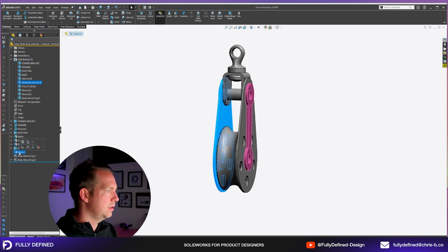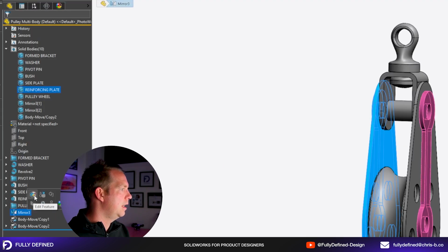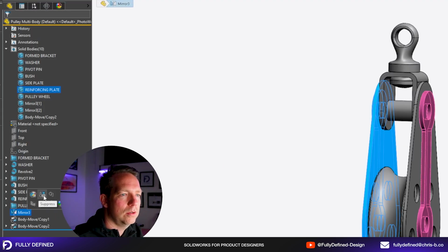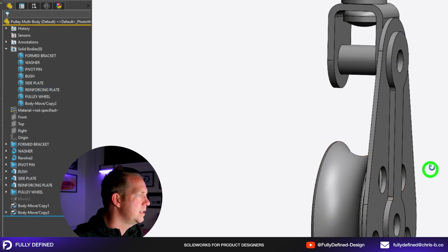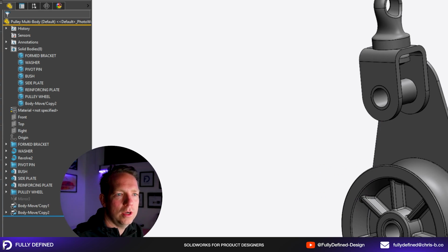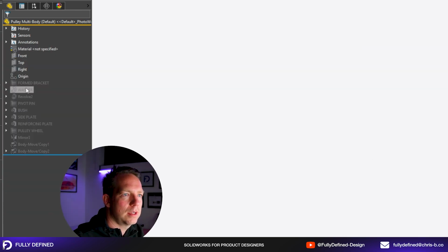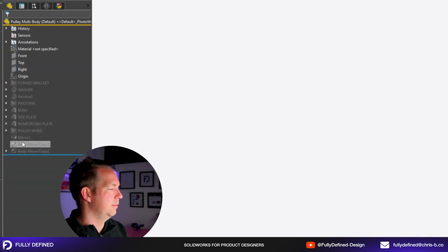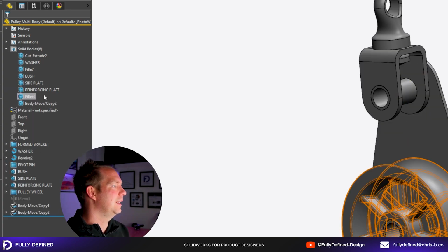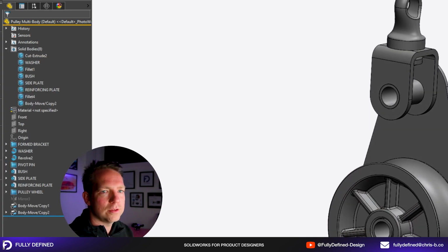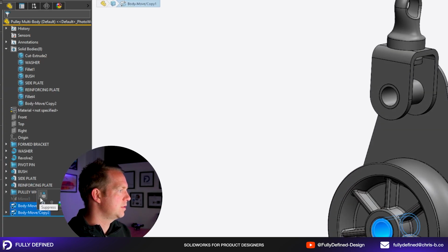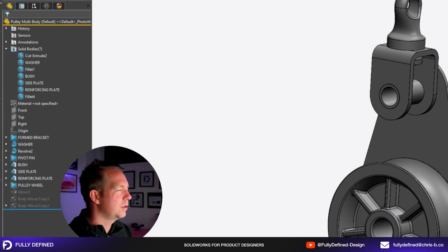You click on a feature in the feature tree, and on the shortcut bar here is an option called suppress. When we press that, it's going to suppress that feature, which is basically turn it off. Now you can do that for any of your features, but you'll find that if you do it for stuff early on, it's going to roll all the way down your file if other elements of your modeling have been related to those features.